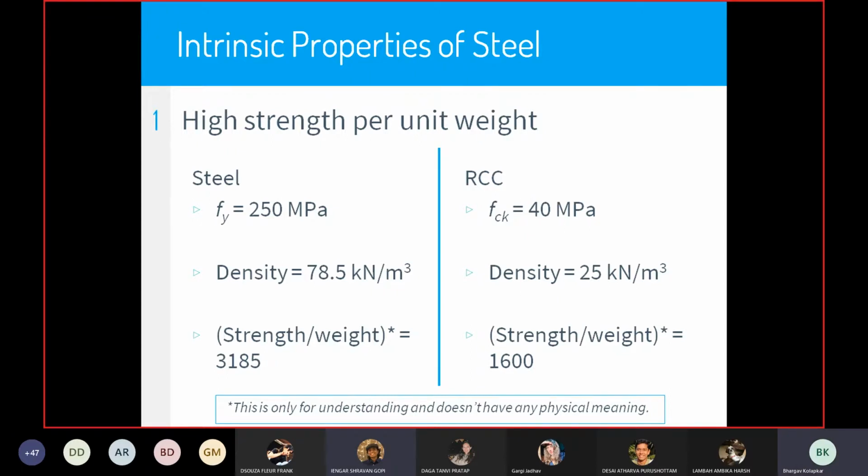Very good answer, both of you. What it necessarily means is that to take a certain amount of load, now you need lesser cross section, which means now you need lesser weight of the structural material, which means that overall your structure is lighter. So, when you compare apple to apple, just in terms of how much the structural system weighs for a particular building, say you have a choice of constructing a building in steel and a building in concrete, everything remains same, only the structural material varies. In that case, you can expect the structure that has steel to weigh lesser as compared to the structure that has concrete. And that helps us because naturally a lighter structure is going to need a lighter foundation.